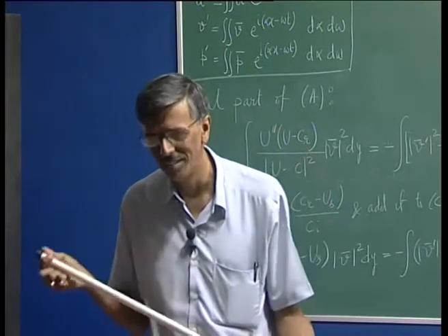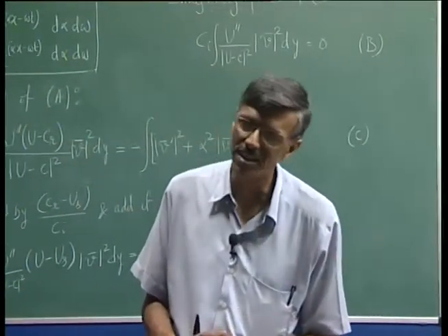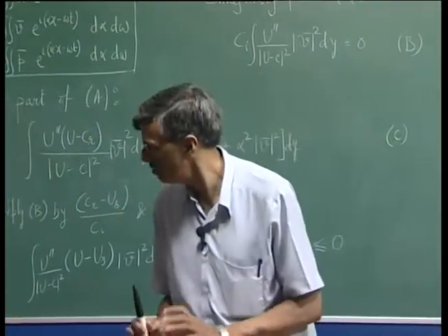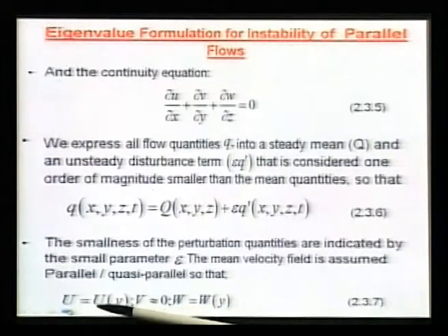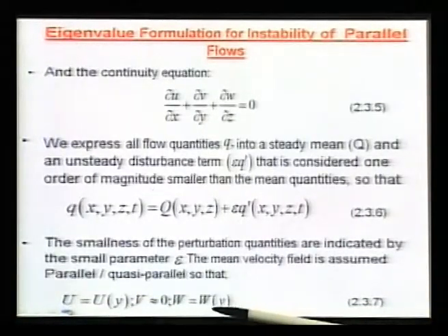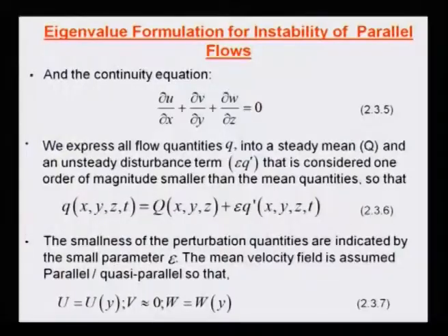Most of you have done the computing course, you know that vector potential is a generalization of stream function in 3 dimensions. Okay. Do not worry about it, we will not get in there unless we come to genuine 3-dimensional flows. At this point in time, let us just simply appreciate that for the parallel flow approximation to hold, we will make capital U a function of y, capital W a function of y. Such an assumption is called the parallel flow approximation or quasi parallel flow approximation.